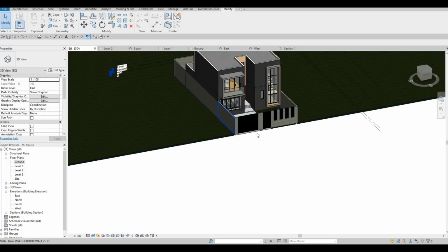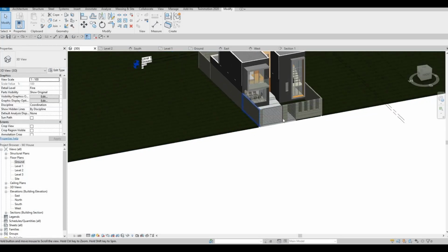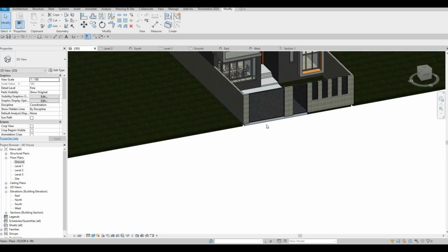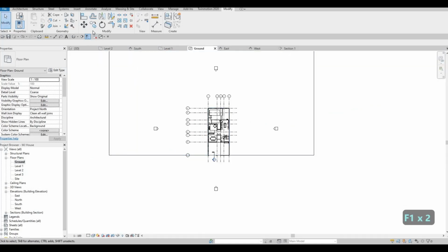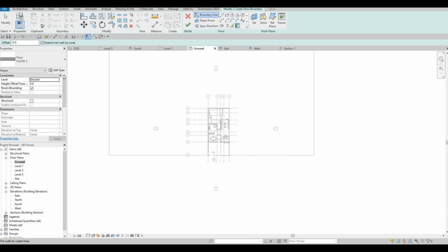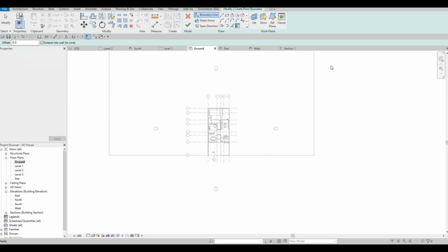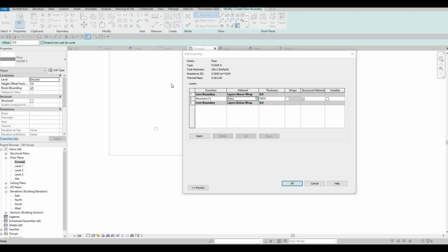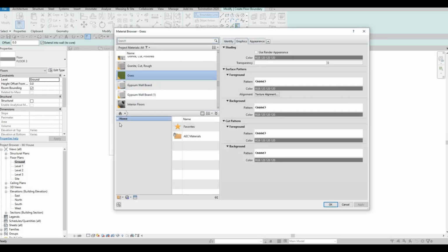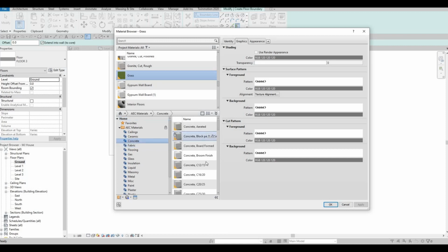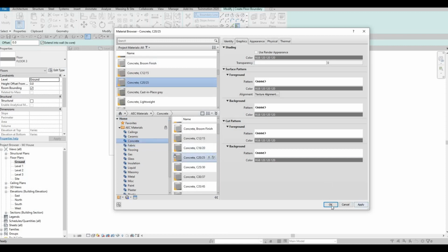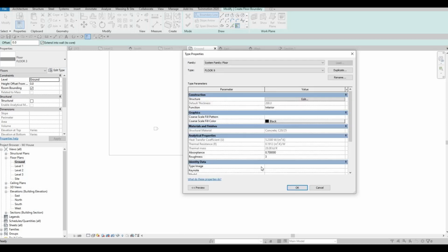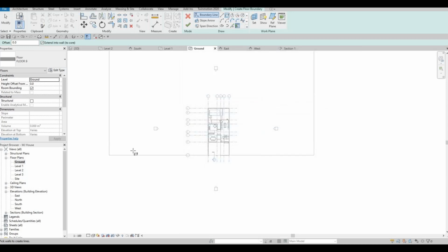What we're gonna do is add our sidewalk right here. So what we're gonna do is create another floor, and then we could just add a sidewalk. So edit, duplicate, this will be floor number 9, and then let's change this to concrete. Let's choose a concrete material that we haven't used, and then just place it into our site.